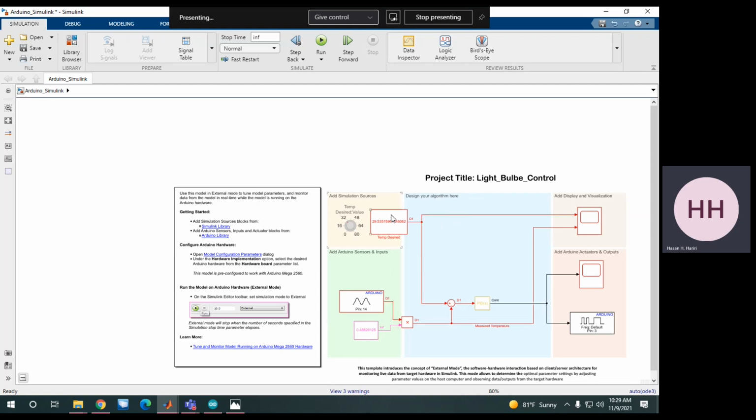Second, it's easy for interface. As you can see, we are not writing code with special syntax, restricted with letters and sentences or special words. Here we are building a block diagram. For example, here we have the summation block, here our PID block, and it's sending the output going to the plant. So the output goes to control our Arduino, or mainly the pin that is connected to Arduino, on pin 3, the PWM pin.